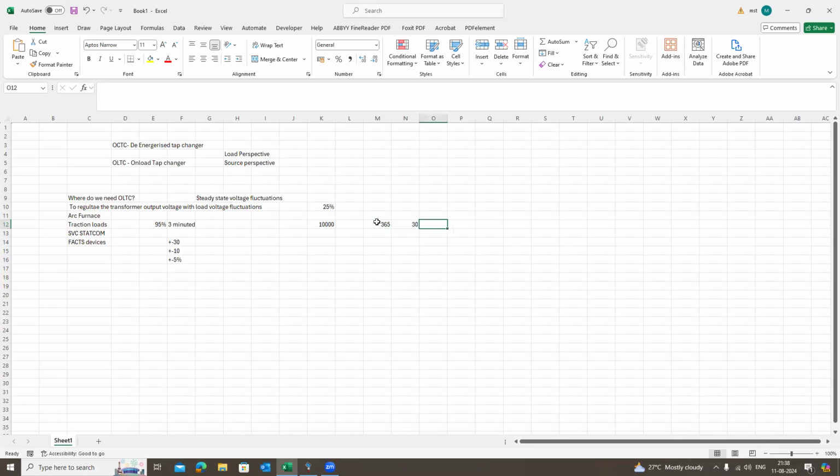So what I mean is, if you do one operation of the OLTC every day, then for 365 days you will obviously be doing 365 operations, and that is the number of operations in a year. So for 10 years, obviously it will be 3650, correct? Yes, sir. 3650, then 30 years you can do that. And typically the transformer life is also in the range of 30 to 40 years. And if you are doing more operations, then much before the end of life, you need to probably do something for replacement of this on-load tap changer.